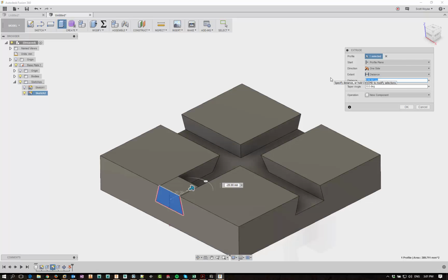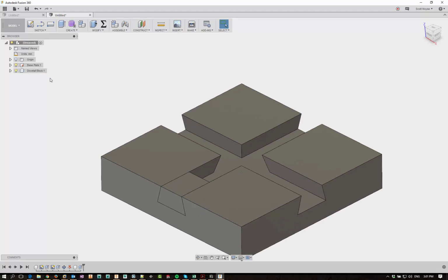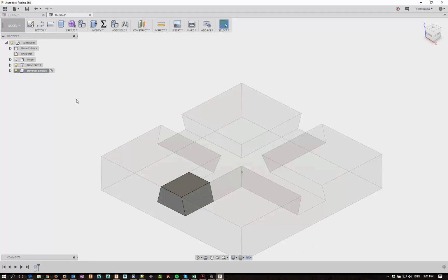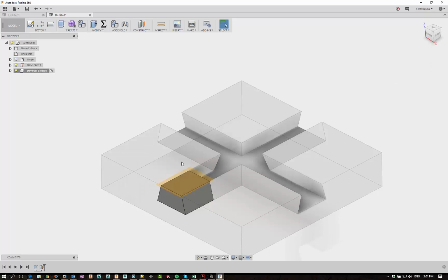and we're going to go minus dovetail width, turn off that dovetail block, and then edit this and put that hole in there. So pull up a plane off here, 1mm, just to allow for that washer. I'm not going to actually model that washer.